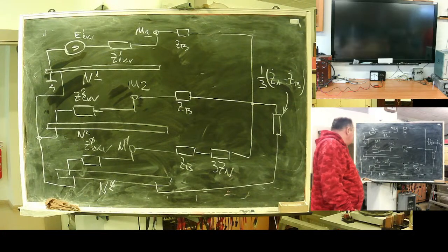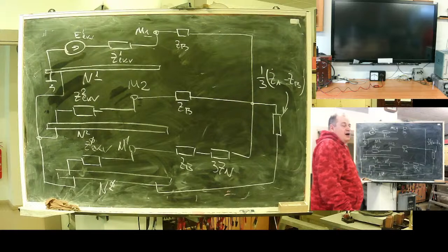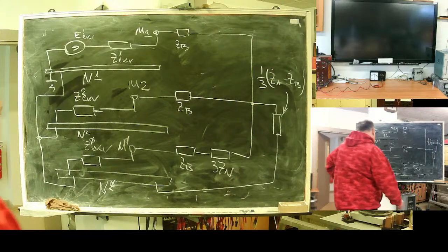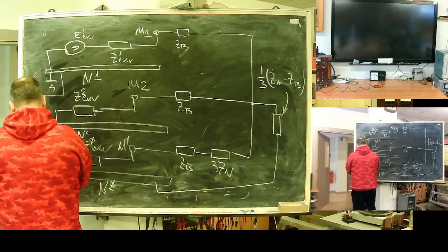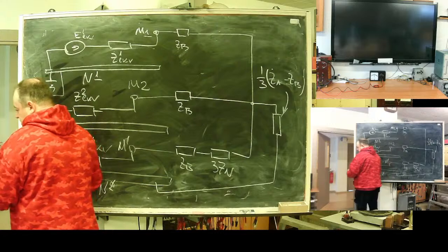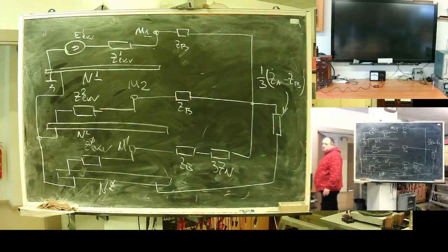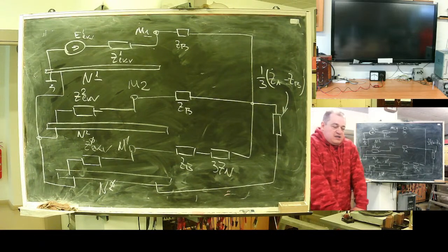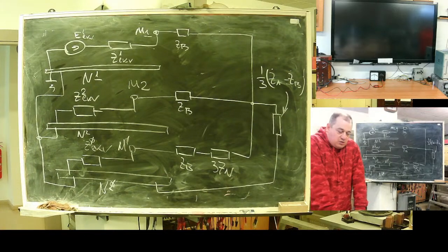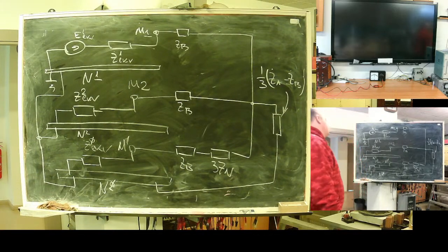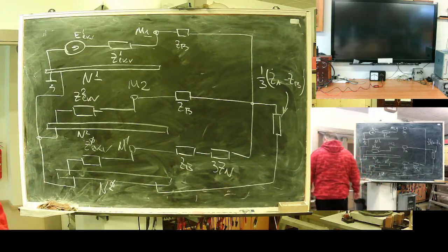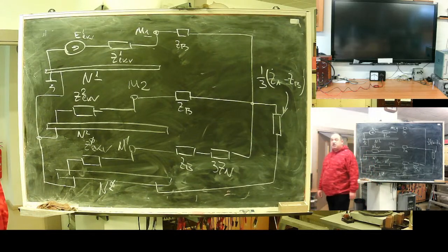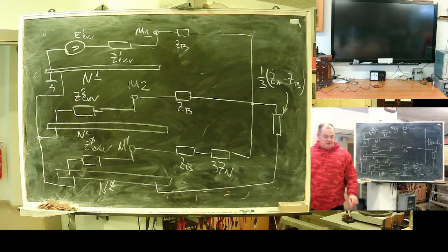Special kinds of tasks are line interruption tasks. A special kind of protection is line interruption protection, because a non-symmetric regime or non-symmetrical mode is dangerous for asynchronous machines. It's called overheating. Especially on expensive machines.